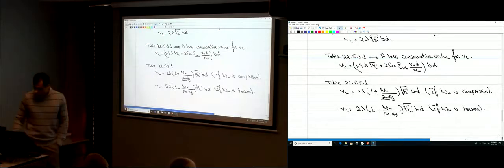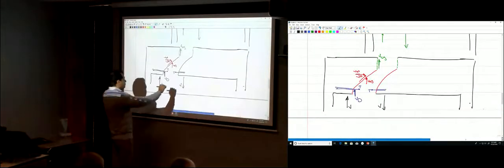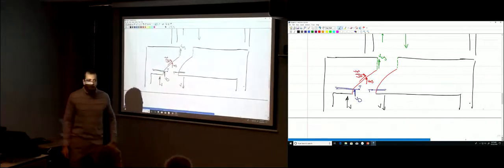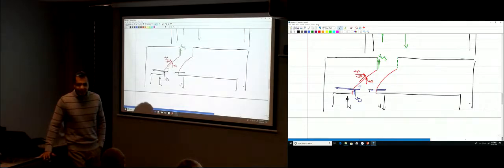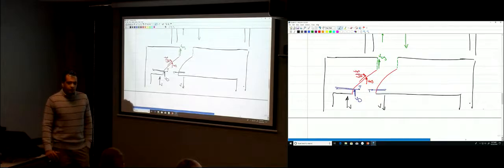What if the shear force applied on that section, this shear force that wants to break the beam along that line, is larger than that VC? What will happen? It will break. What's your job now? You need to make sure that it doesn't break, right? So you said, okay, increase the dimensions. No. Just a bit more steel in it.